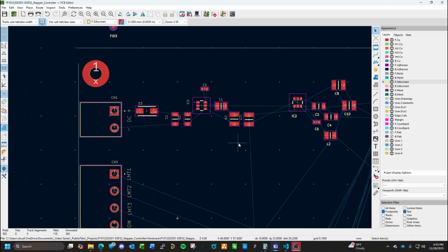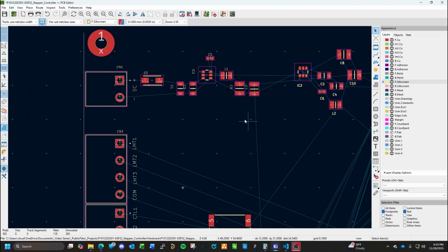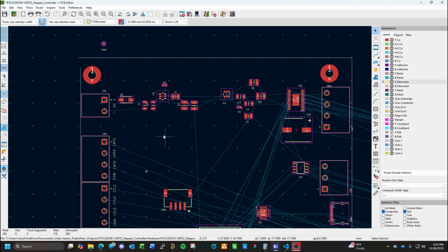What we could do if we really wanted to is take this power supply and build it up under here, and maybe that's what we'll do, and we'll have the 24 volt come down here to feed this power supply and that power supply, and then also come up over here to the motor controller. Maybe that's what we'll do, because we can put the opto isolators on the bottom of the board if we don't feel like there's enough room. We may not actually need to populate the bottom of the board. Right now, it's kind of looking promising.